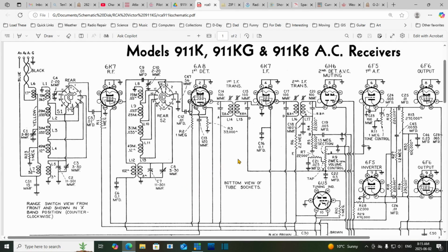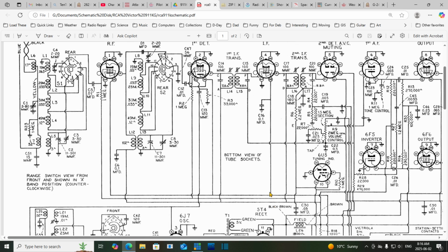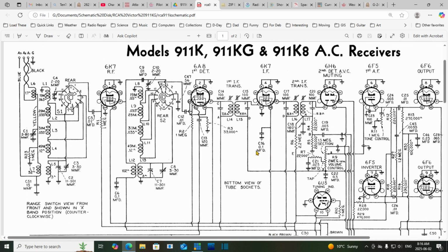Okay, so first of all, is it this one? No. Well, one end goes to ground, the other end goes to a switch. Oh my gosh, and all by itself to a switch. Maybe we can start by looking at the switches and come out of there. No big capacitors here. Next switch, 0.01 picofarads, 0.01 picofarads. Anytime I say picofarads, what I'm really saying is probably a mica capacitor.